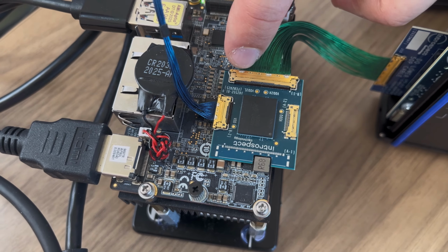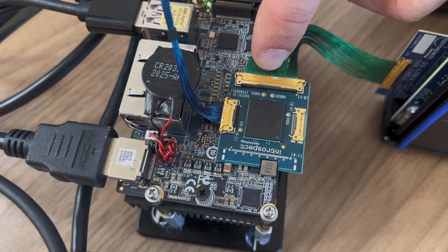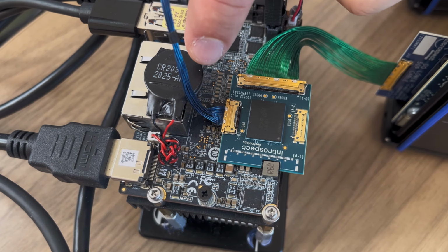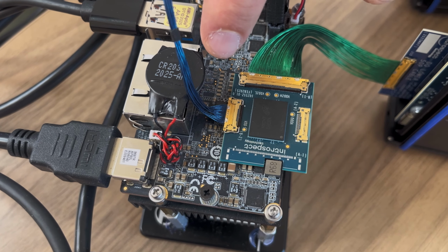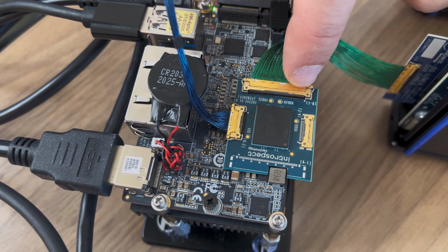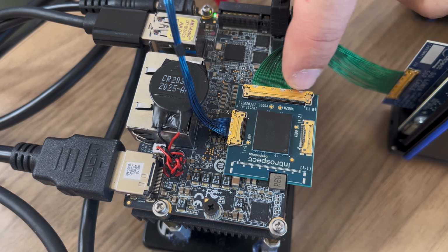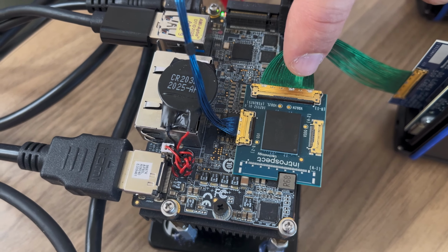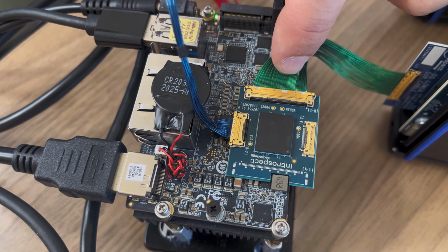So here we're showing the DQ signals in this green cable assembly and the CA signals in the blue cable assembly. And because it does not require any soldering and everything is embedded inside the connector, you get very high signal integrity and very low noise coming out of this interposer. The signals coming out of the interposer are going to two RSH devices. These are remote sampling heads, and they are active probe solutions that provide access to 12 channels simultaneously.